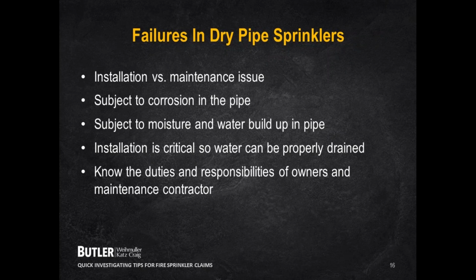What it is, it's a low point and it's a valve, so that the landlord, usually say there's a building engineer or a service maintenance person on board at the property, has to go around periodically, check these low point valves and drain water off of them to keep them free of water.